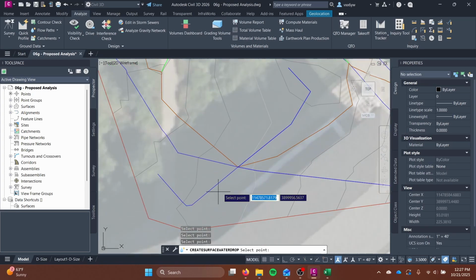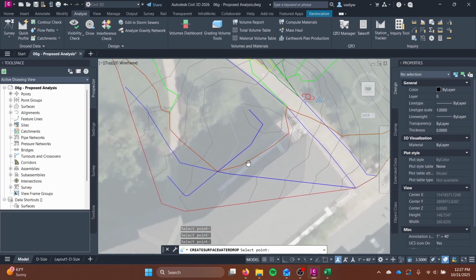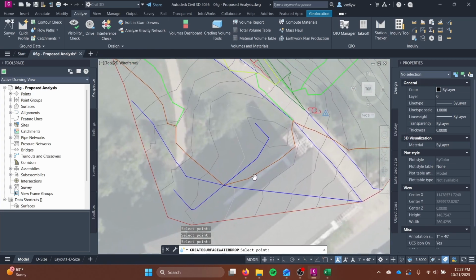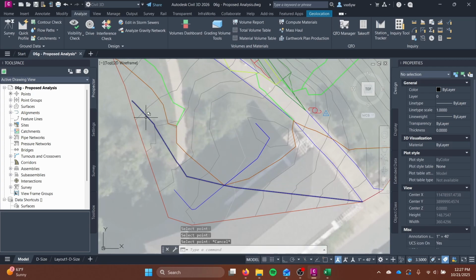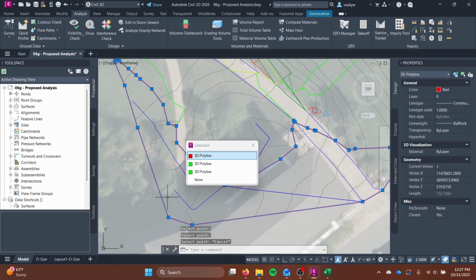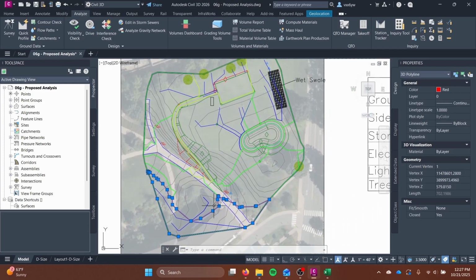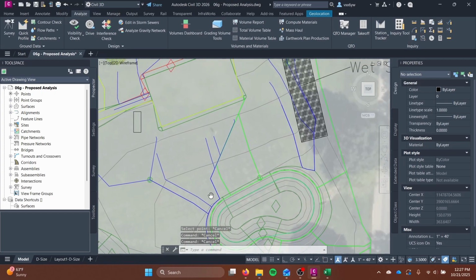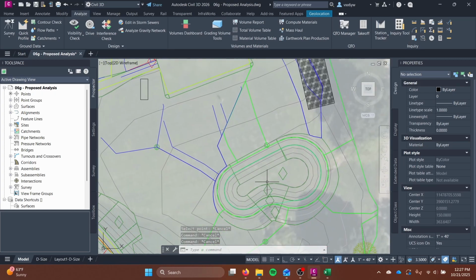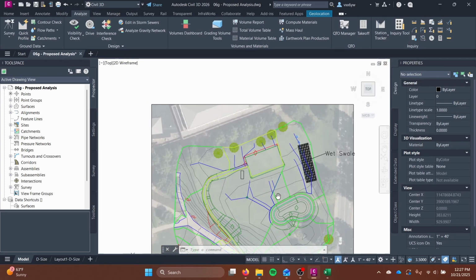If you have any multi-drains like I do here, I would just pick and choose which one you have it going into. So I have it here as this entire area will flow to this point. That's not strictly true, but the total runoff will be the same, so I think that's okay. Again, think about those BMPs and how those account to your runoff coefficients.